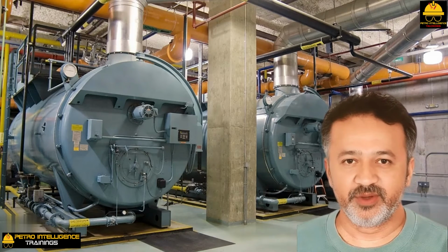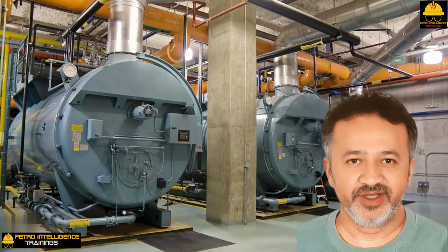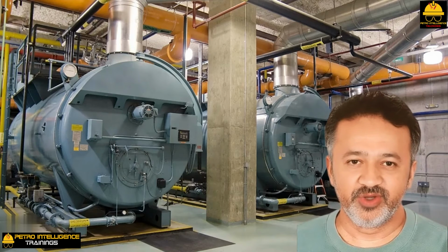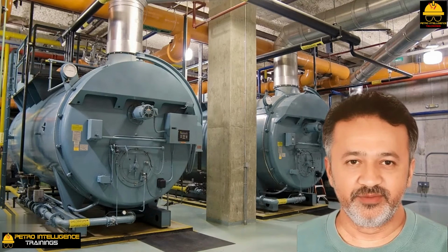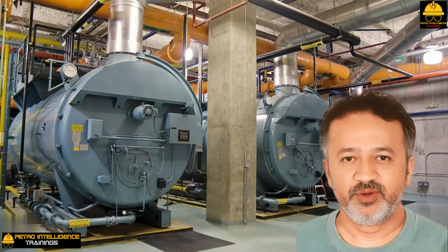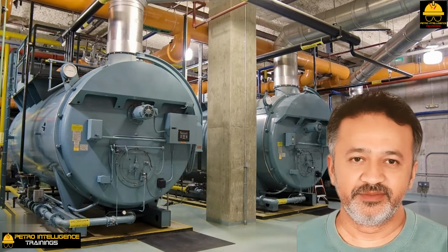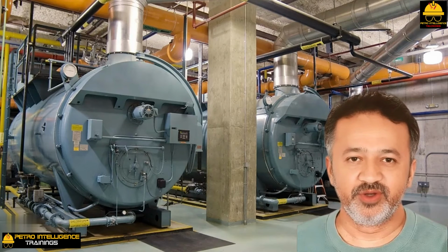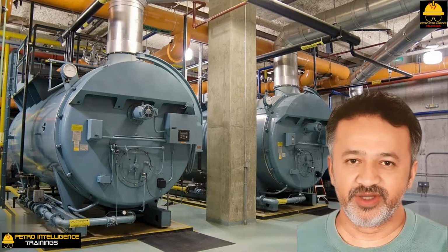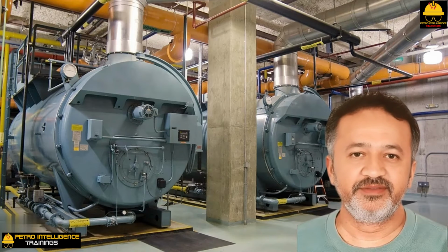Demineralization of BFW. The main advantage of cation-anion ion exchanger resin demineralization over phosphate treating or hot lime softening of boiler feedwater is the superior reduction of silicates in steam. Silicates deposited on steam turbine blades may lead to a loss of turbine efficiency and vibration, and also stress corrosion and sudden failure of the blades.